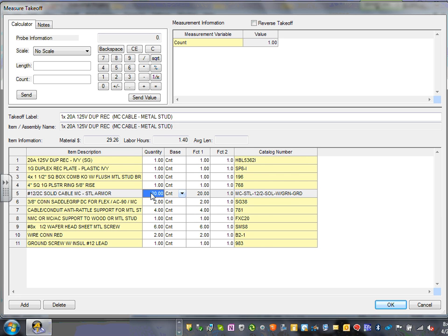So all you have to do now is take it up to the ceiling, tie it to the conduits, put your boxes in the ceiling, and take them all the way back. So Adam, if you do that, you don't have to take the wires between the receptacles. We're doing them all the way, looping them in the ceiling. Done. Makes it easier, right?